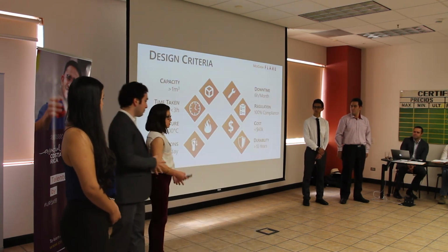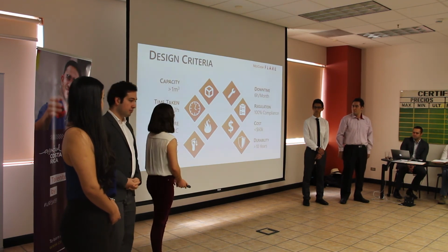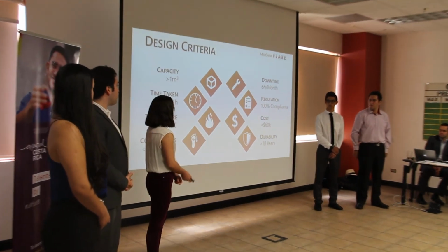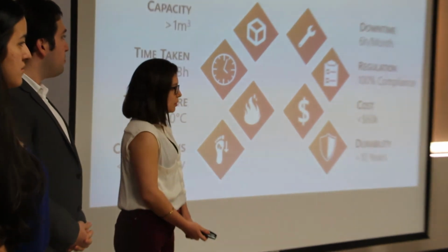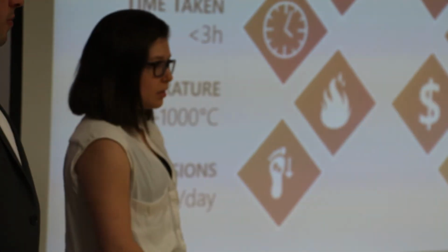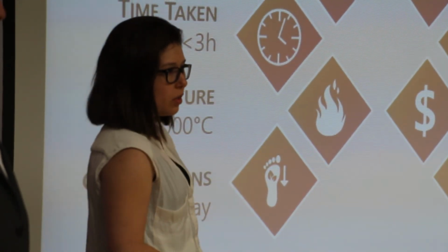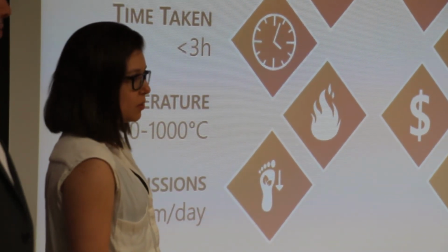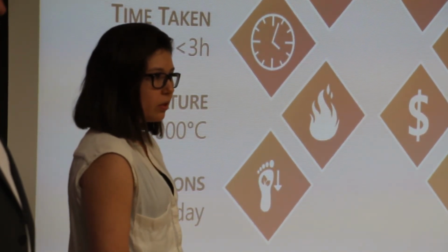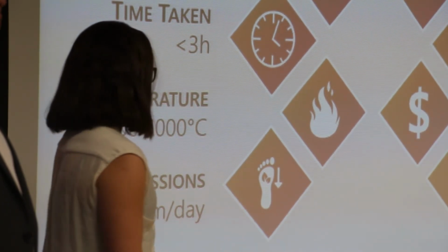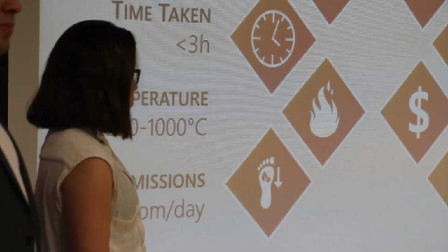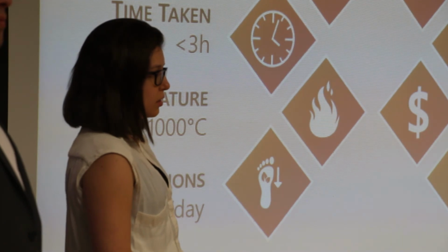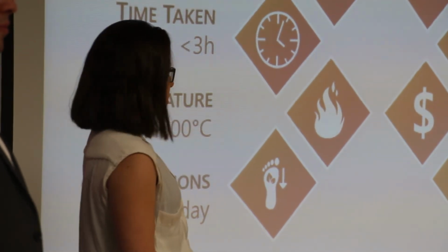So for this, we established a design criteria. The first is the device must have a capacity of 1 cubic meter. It should take less than 3 hours to complete all the process and burn all the tissue. It must reach temperatures between 800 and 1000 Celsius. The CO2 emissions should be less than 20 ppm per day.